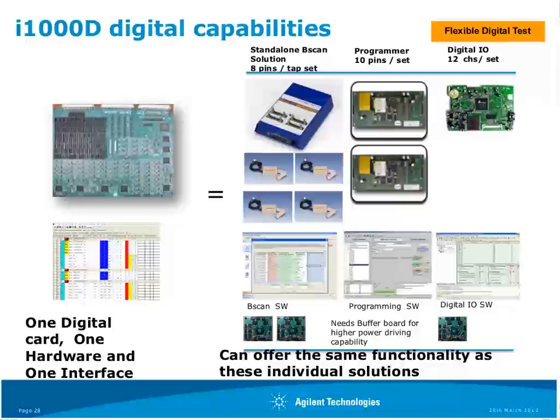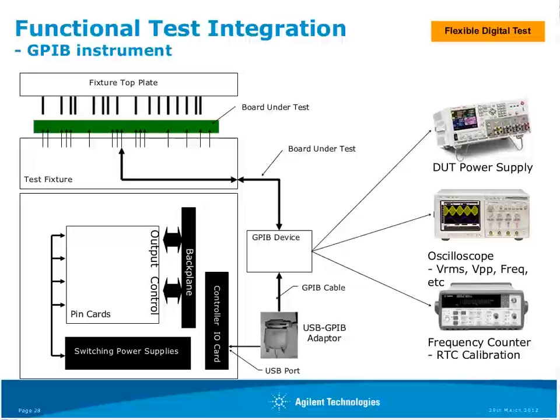That brings it all into one single platform, and that saves engineering time as opposed to doing similar repeated tasks using multiple platforms or trying to wedge different hardware into your fixtures. It's also capable to add in functional test equipment and make calls through GPIB. So when required, if we want to bring in tests from functional tests, we can bring those in as well and communicate using I/O libs and the GPIB communication.